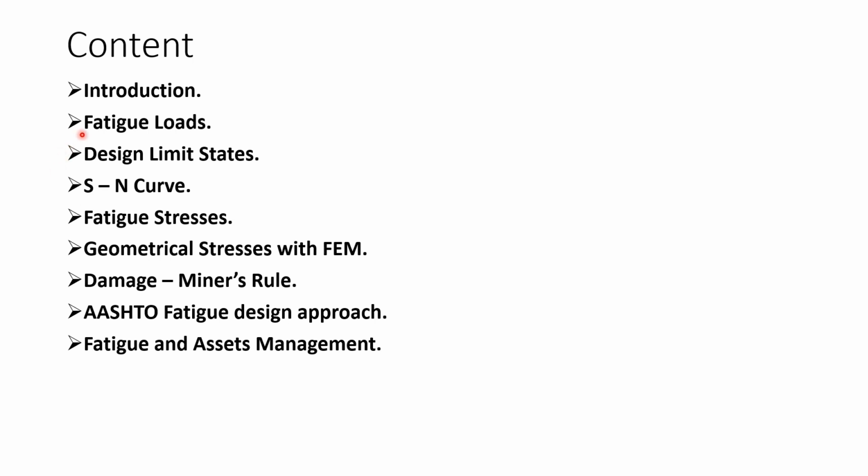In the fourth section, we get more detailed about fatigue design, starting with explaining the S-N curve and the key definitions that are widely used in most of the reference books that talk about fatigue design. After that, we reach the fatigue stresses section, which explains how to process stresses to be able to perform fatigue design, and then gives an overview of how the international codes like the American, Australian, and Eurocode classify the fatigue stresses and relate them to different modeling levels.